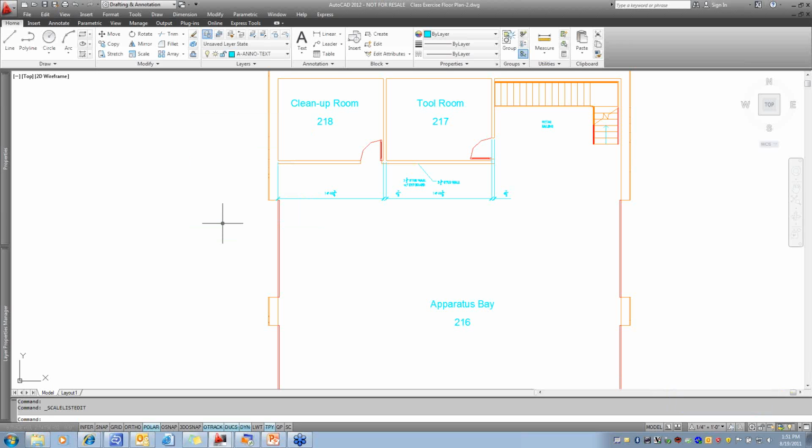Great. Okay. I have one last question here for now. Are attributes annotative scalable as well? Yes, if you were just putting attributes and it wasn't a part of a block, those attributes could be annotative also. But generally, it's the entire block that's going to be annotative. Whatever block you're creating to use those attributes, yes, those can be annotative also.